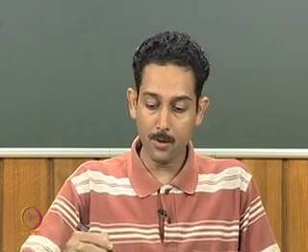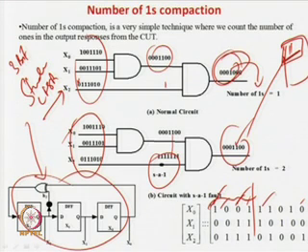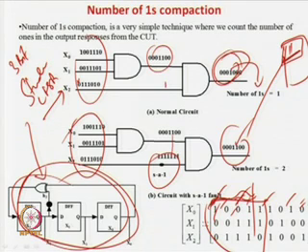That is why it becomes a very important design challenge that, given a compaction technique, or sometimes you may have to change the compaction technique. For example, if you know that applying these alternate patterns takes a long time to generate, you can ask whether you can have at least up to this number of patterns, so that you can generate them very quickly from this LFSR, but the compaction technique still gives a small amount of aliasing.